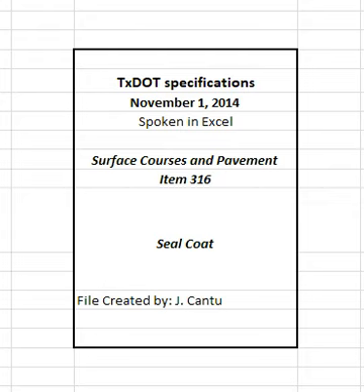Upon work completion or temporary suspension, any remaining asphalt material will be weighed by a certified public weigher, or measured by volume in a calibrated distributor or tank and the quantity converted to tons at the measured temperature. The quantity to be measured will be the number of tons received minus the number of tons remaining after all directed work is complete and minus the amount used for other items. 5.1.3 Quantity adjustments. When shown on the plans, the measured quantity will be adjusted to compensate for variation in required application or residual rates for different types of asphalt.